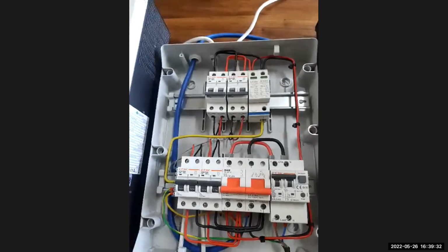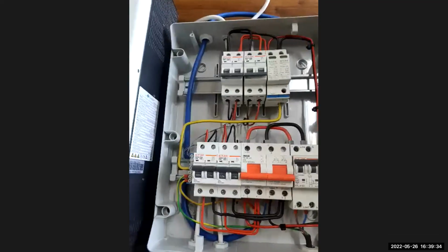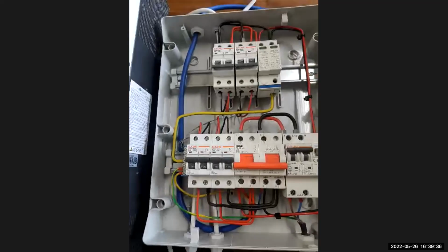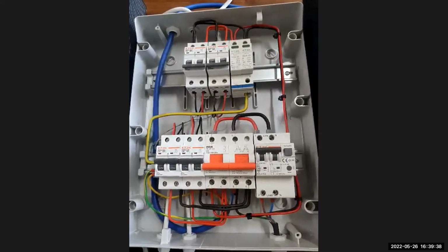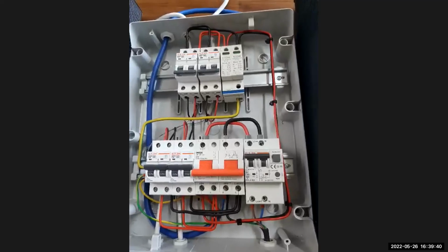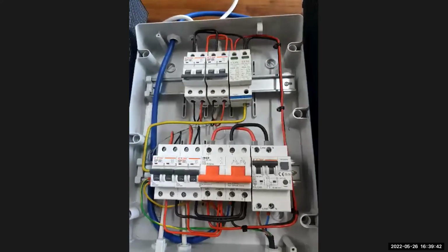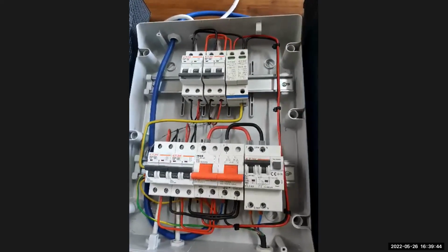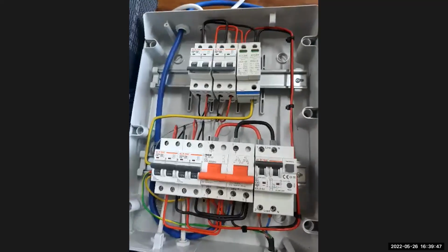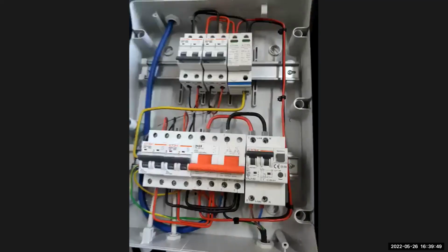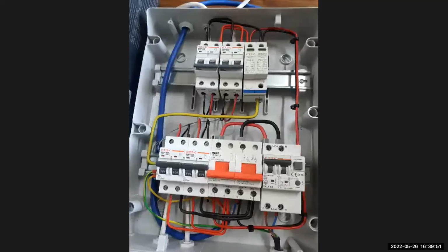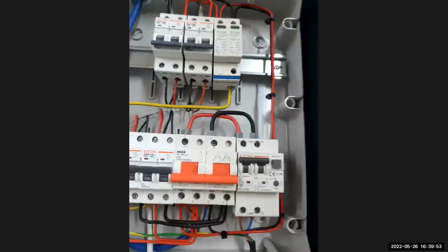So you give it a one-phase parallel system or a three-phase parallel system. So you have to assign all the inverters to a parallel setting. So you can't just do the first one, and then the rest of them will accept the setting. You have to go to each inverter and physically do the settings on it. Okay.